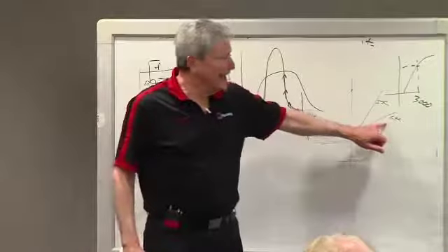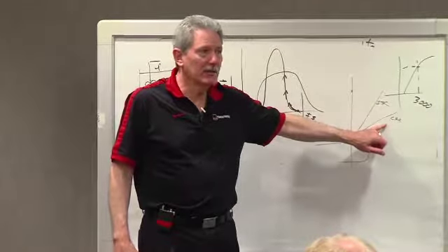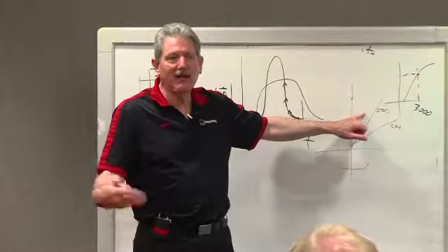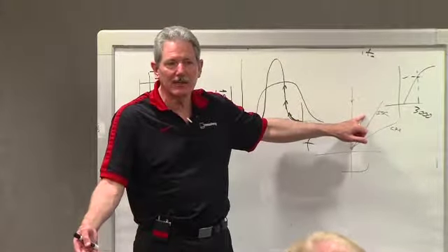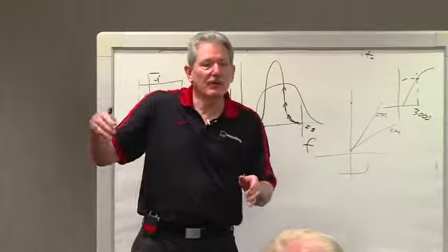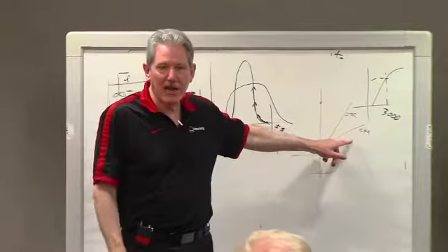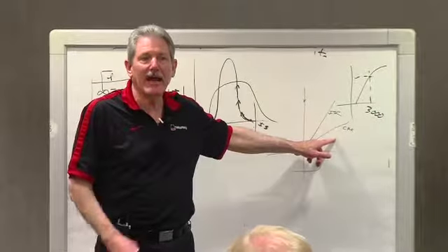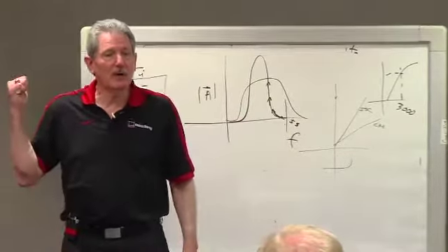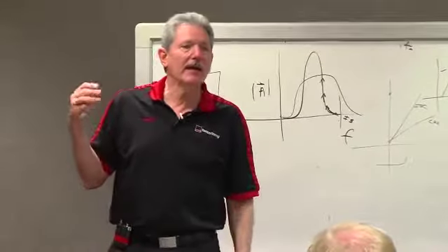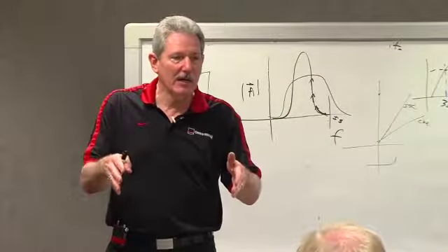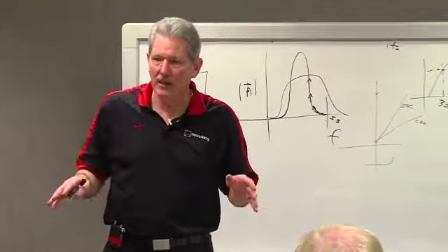As long as your damping element is slower than your idle speed control, you keep it in a critically damped or an over-damped condition. You take it from under-damped to over-damped or critically damped. So this damping of load response control is now being seen to have many uses. We had one with Hyundai last year where they had an idle stability problem, not related to any of the things I've told you. We dropped the LRC on it and it went away.